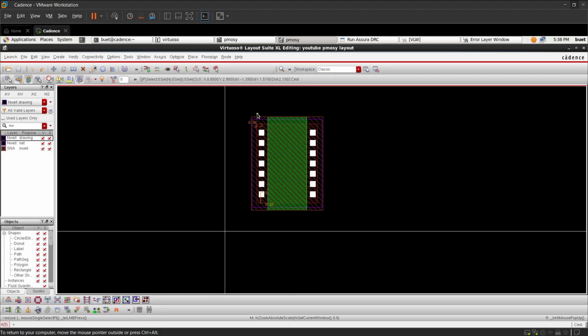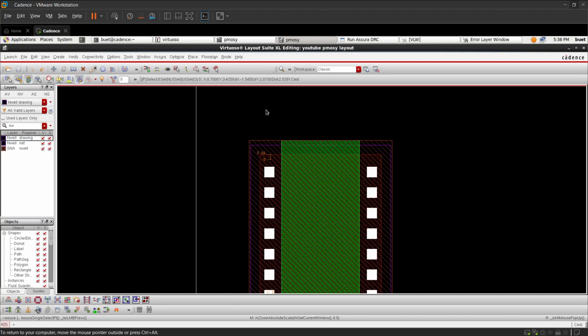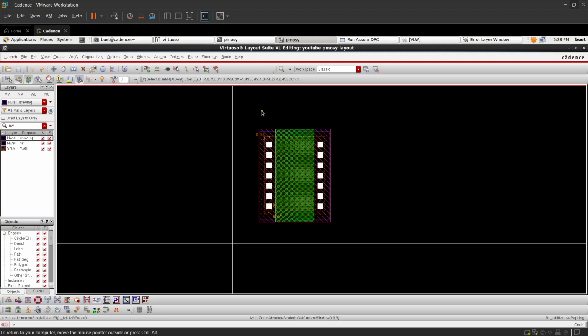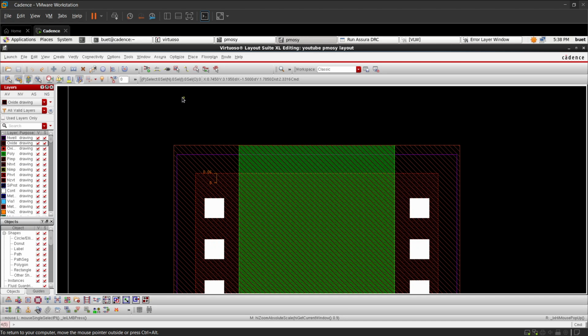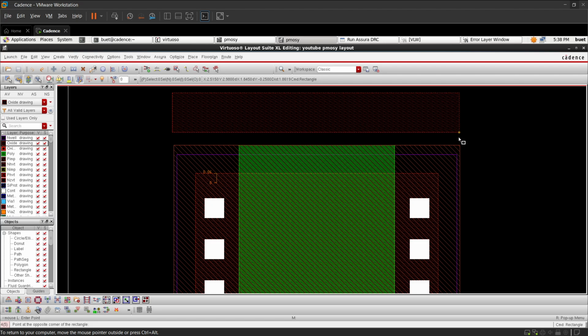There are many problems that arise during a fabrication process. So to reduce that latch up, we are supposed to form a P tap over here. For that, again go to oxide. Oxide will help you out to do the isolation. Click on R, done.